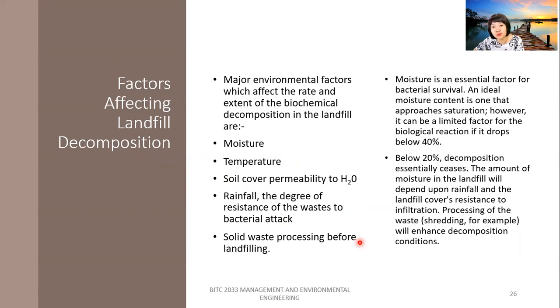Because when we have too much moisture, the landfill will degrade at a faster rate. Also, when you have high temperatures, it will have a faster biodegradation process, so the settlement will be higher. That's why we need to do the compaction to remove the moisture. But where does the water go after we do the compaction and the moisture goes out? You will learn it in the next part.